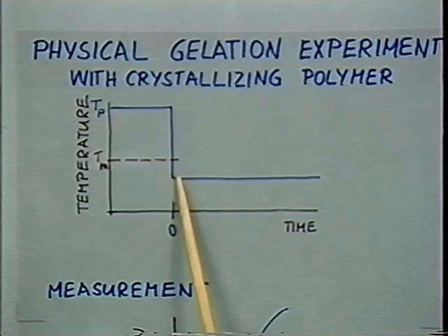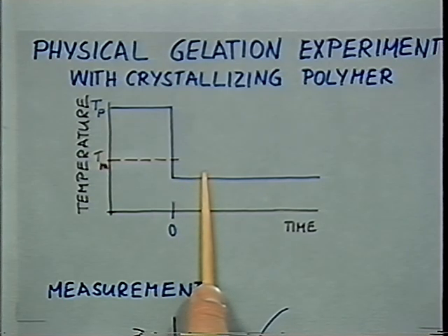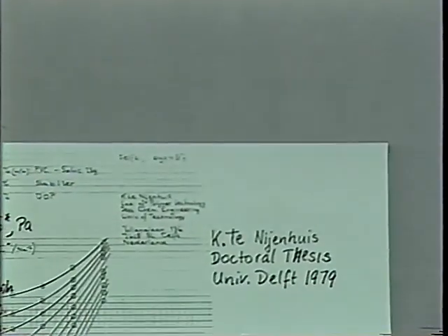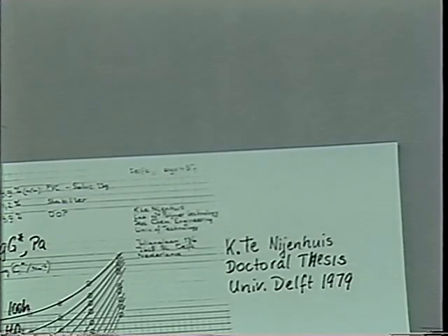It was 90 degrees, and then followed the evolution of G prime, G double prime during the aging process. And he found that after about 45 minutes, his sample underwent a liquid-solid transition. The polymer which he used was a PVC, and he plasticized this with DOP.